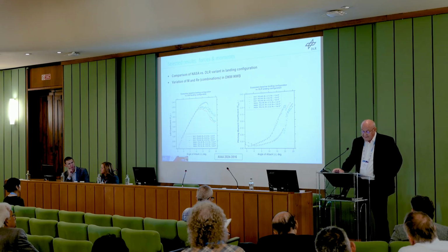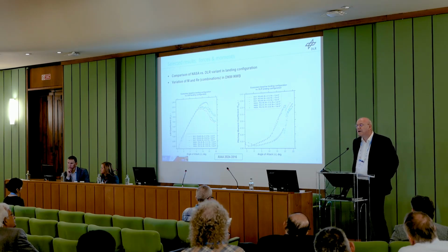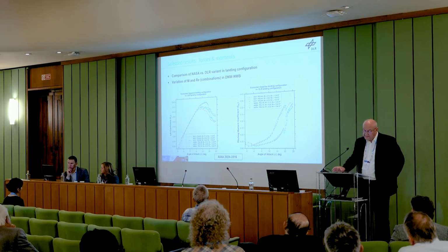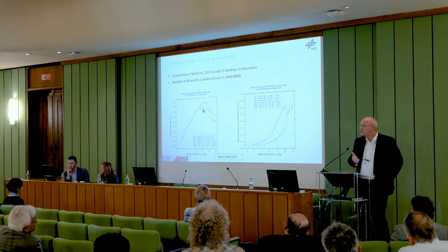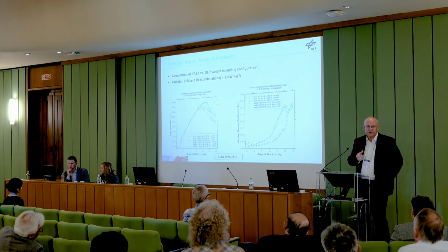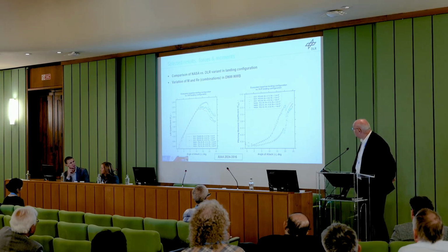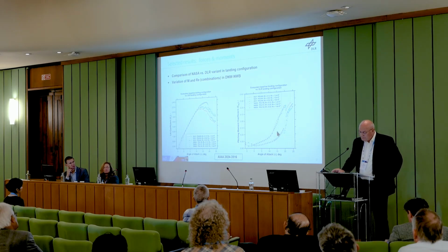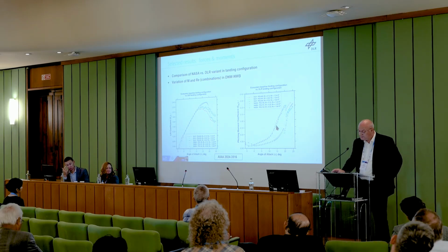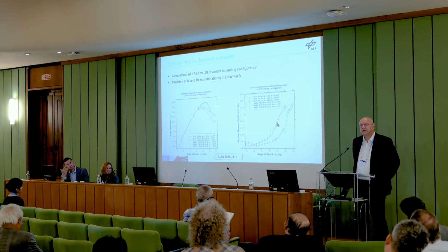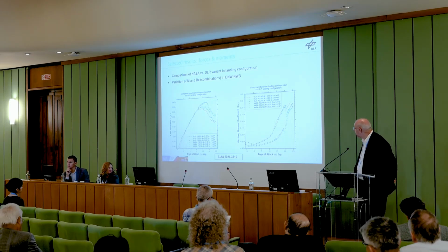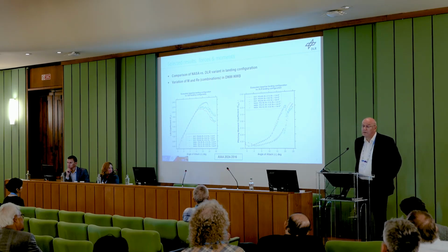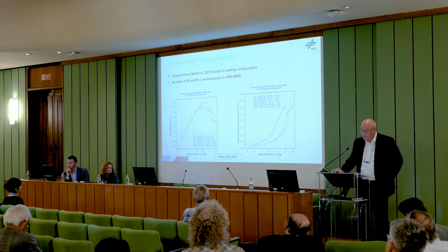The trends here in terms of this Mach Reynolds number variation, which again is very mild, is consistent. So the higher the Mach and Reynolds number, the higher CLmax is. The differences are somewhat larger for the DLR configuration than they are for the NASA configuration, which tells us that this outboard separation is low Reynolds number induced and tends to react more on the Reynolds number variation than for the slat. Pitching moments are very comparable. Differences are small. In general, we have a little bit less nose-down pitching moment for the DLR configuration, which is good in principle for trim efforts, but not decisive in this framework.